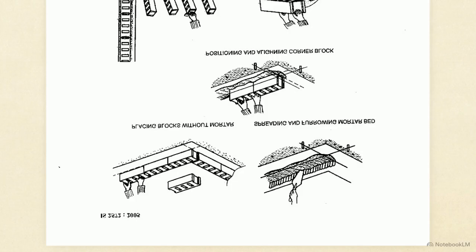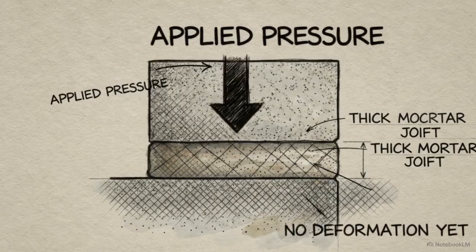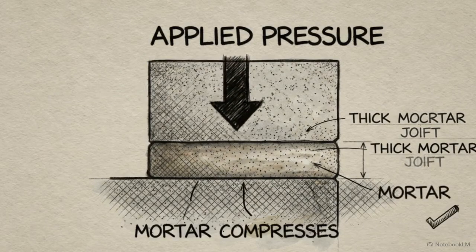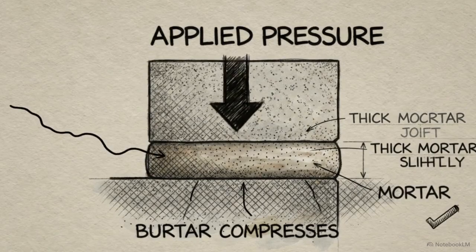For heavy load-bearing construction, full mortar bedding spreads the mix evenly across face shells and internal webs. For non-load-bearing walls, face shell bedding is utilized. Mortar is applied only to the outer shells, leaving internal webs bare to arrest capillary water seepage. In concrete masonry, mortar serves as a flexible, localized shock absorber for the entire wall assembly.